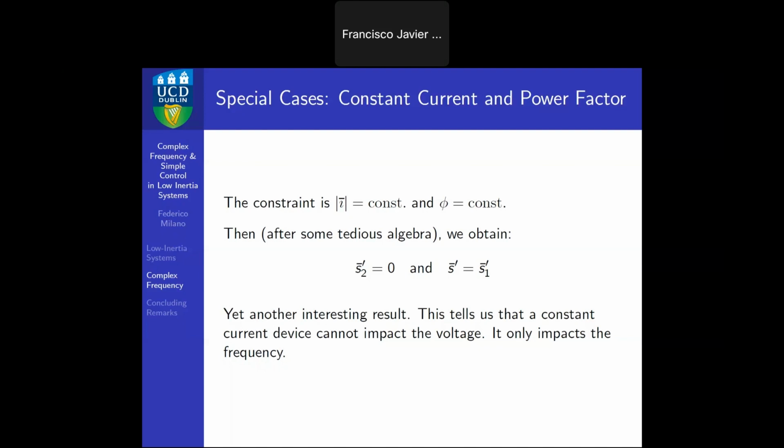But in reality, what you really need to do is then you can be the most effective possible because there is no part of S2. So whenever you want to regulate the frequency with P, what you really should regulate is P1, the part of the S that is affecting omega. But if you regulate only P, you will change P2 plus P1. And so part of the regulation, everything that is in P2, will not be effective, will be lost, like an inefficiency of the control.